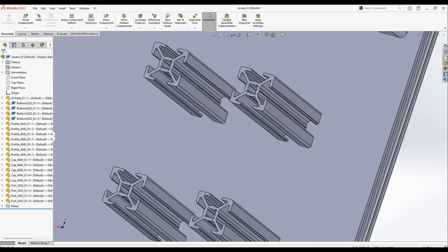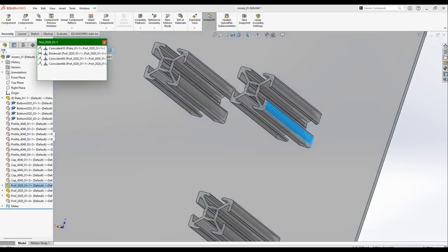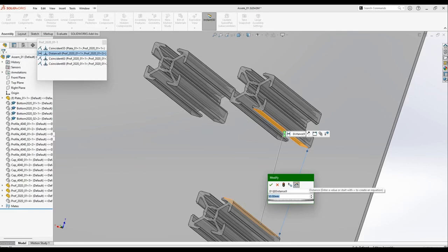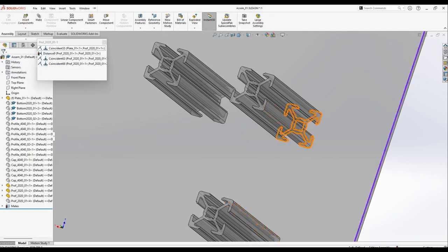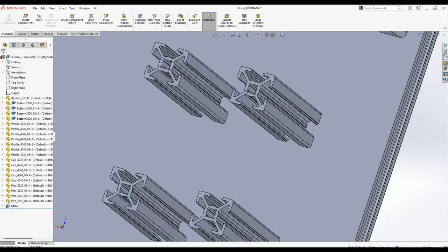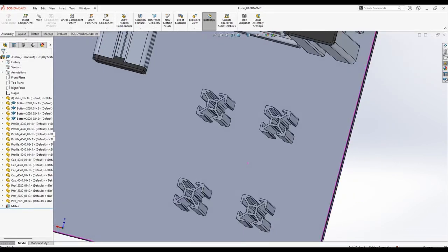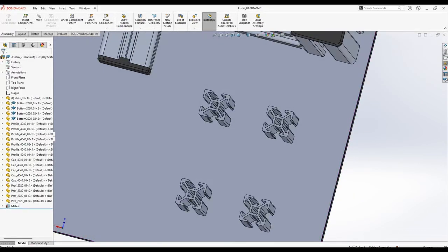So now I need to go back to the 30 millimeters, click to this part, click to view all mates of this part, click to this, double click to this, and I can change the distance to 30 millimeters, click enter with the keyboard, and assign it. I need to assign it, and you see some sign, and I need to recalculate, redraw it, but you see here directly.